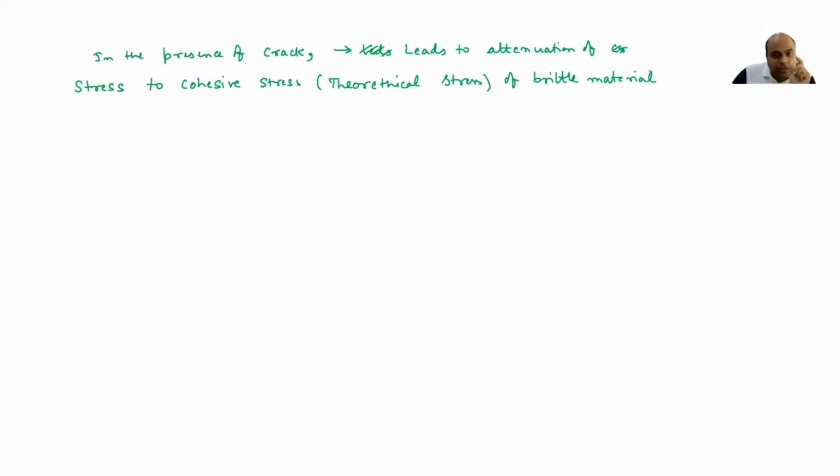Locally you're going to increase the stress. That means there is a stress concentration locally, which can be a very high value, even the theoretical stress value, and then it can lead to fracture.